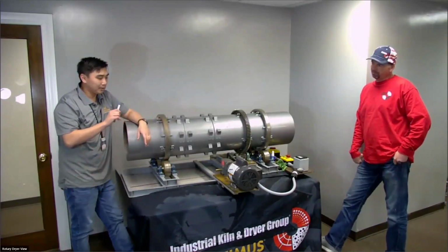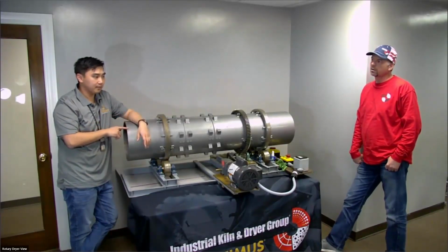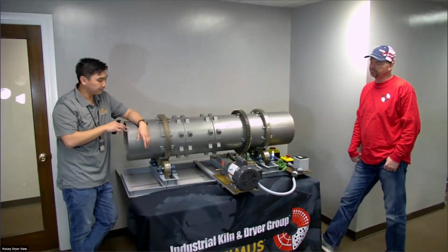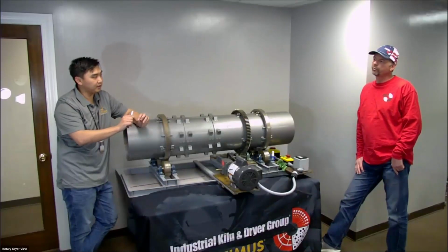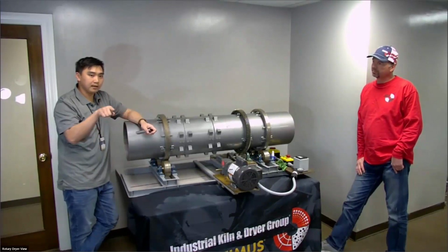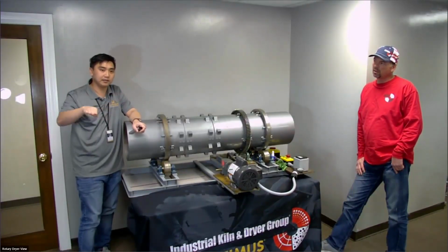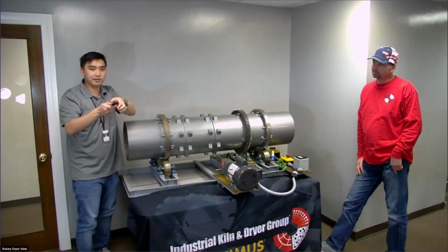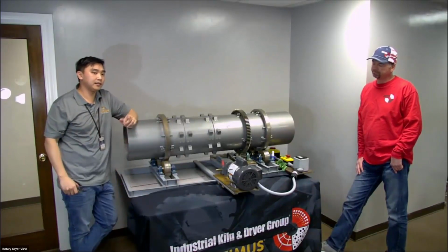Oh yeah. So one of the tricks that we can help you with is if you ever go inside a unit, and this is applicable for anything that's bare metal, so with your dryers, maybe your calciners, right? If there's a very, very shiny spot, that means you don't have even a little angle iron or quarter by quarter inch, anything. Because what's happening is it's doing this motion, and if you keep doing this motion, you have the material sawing back and forth. It's like sandpaper. Actually, if there is sand, it is sandpaper. But if you have something like this where it hits and it goes over, it helps tumble it a little bit, so that should improve your life.